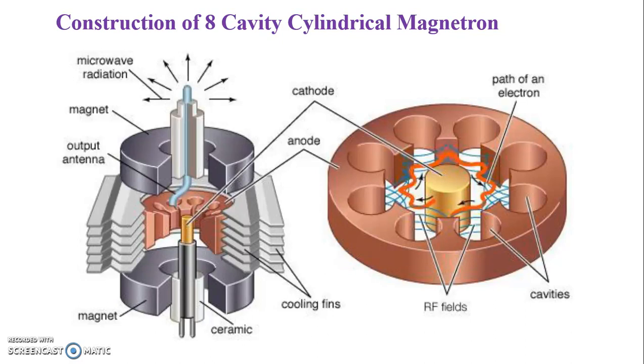It is a crossfield device, as the electric field between anode and cathode is radial, whereas the magnetic field produced by a permanent magnet is axial. The permanent magnet is placed such that the magnetic lines are parallel to the vertical cathode and perpendicular to the electric field between cathode and anode. These are nothing but the cooling fins.